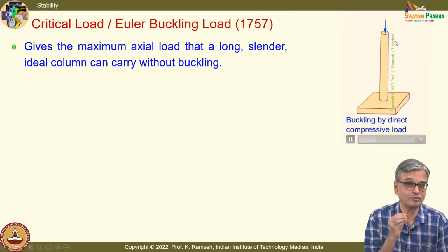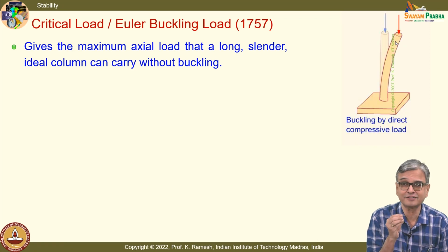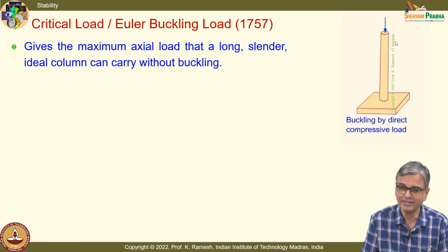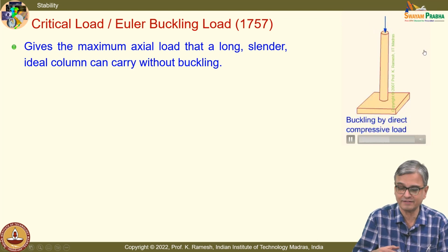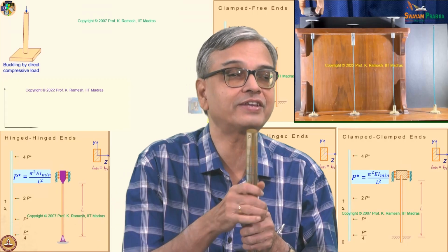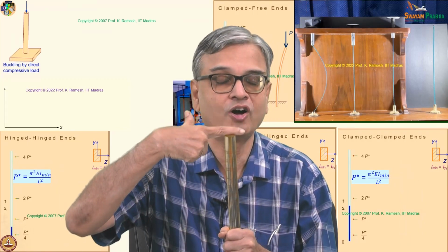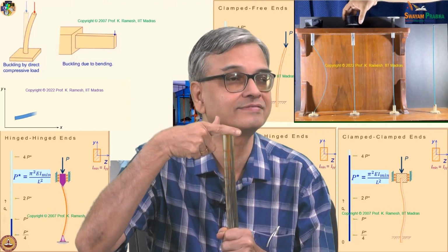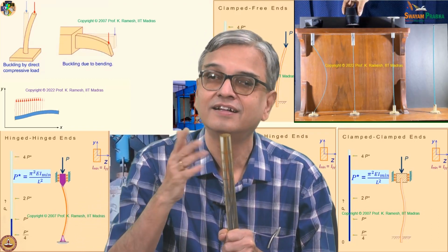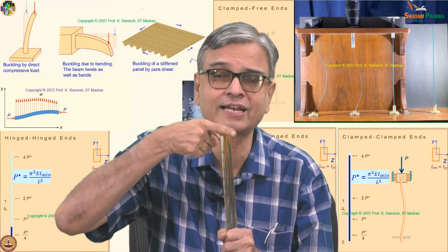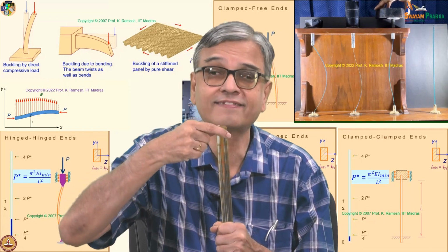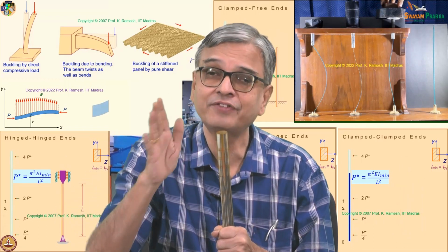I have already told you how the mathematics understands the cross section. How does the mathematics understand the cross section? You have the moment of inertia. Fine. Suppose I take any axis when the geometry is circular. What is the moment of inertia on any of these diagonals? The moment of inertia, not the polar moment of inertia, I am talking about inertia about an axis. Because it is a circular cross section, the moment of inertia is the same.